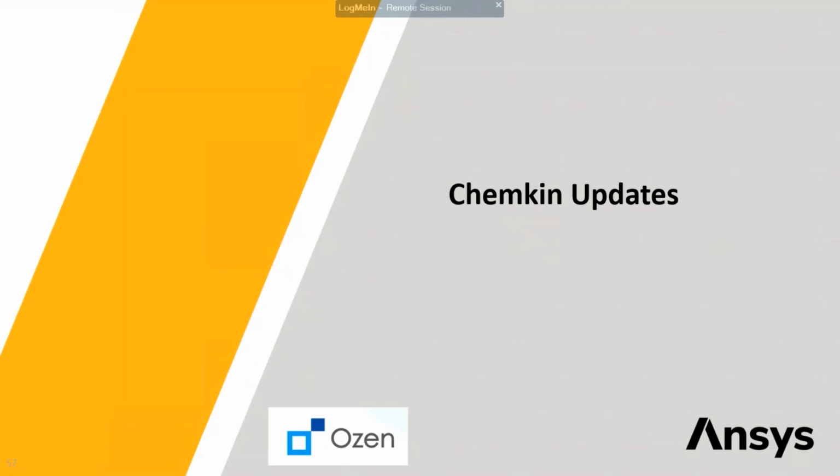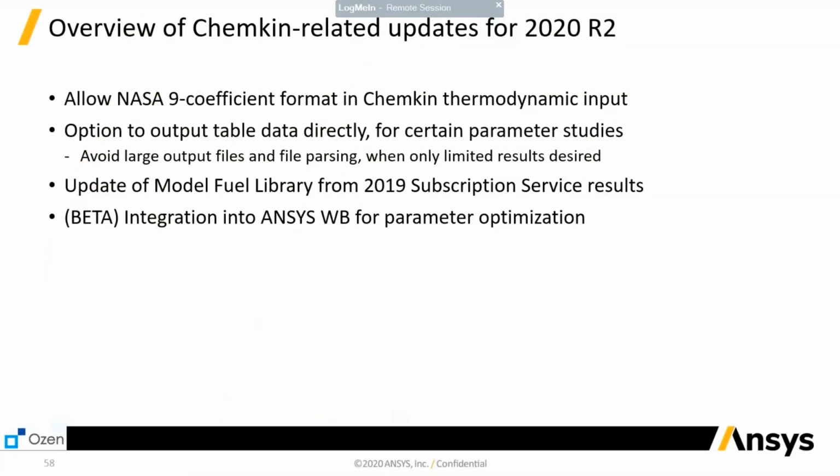time. The other product, which is inside the FPU package and has gone through some updates, is Chemkin. The new Chemkin does allow the NASA 9 coefficient format for the thermodynamics variables that you put in it. It has the option to output tables in an easier way directly, but before you had to get a big output file and then post-process it.